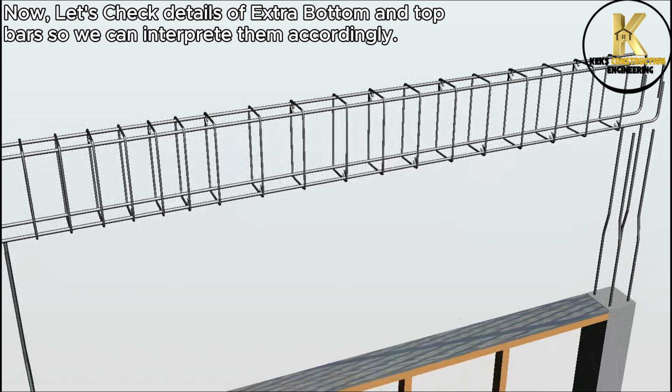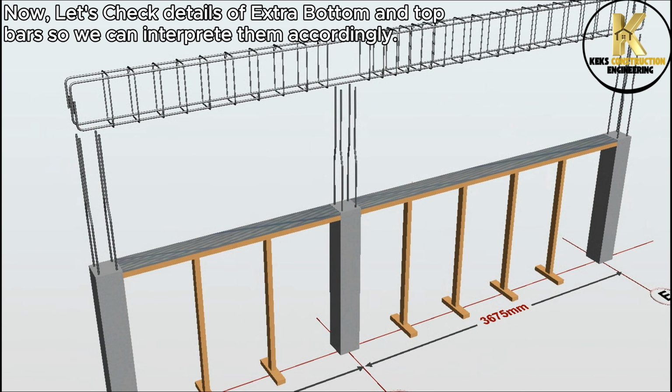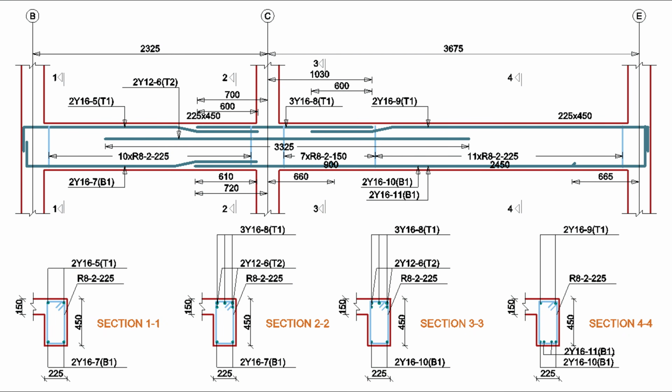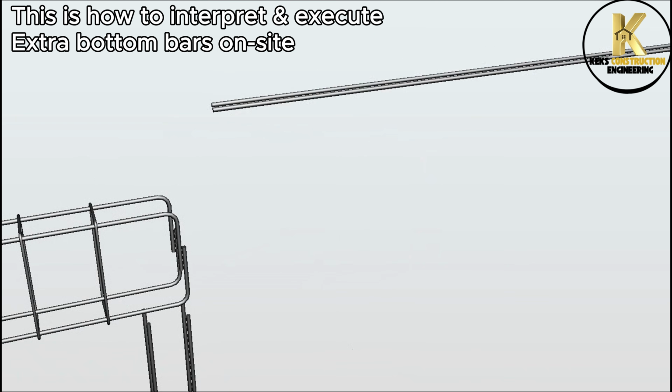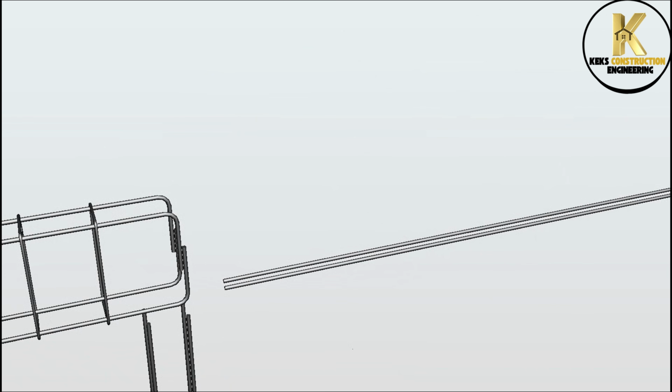Now, let's check details of extra bottom and top bars so we can interpret them accordingly. This green bar below is used to indicate the extra bottom bars required to balance the positive bending moment at the bottom. From this drawing, it's 2 numbers of 16 mm diameter bars. You can also see this bar details in section 4-4 below. This is how to interpret and execute extra bottom bars on site.